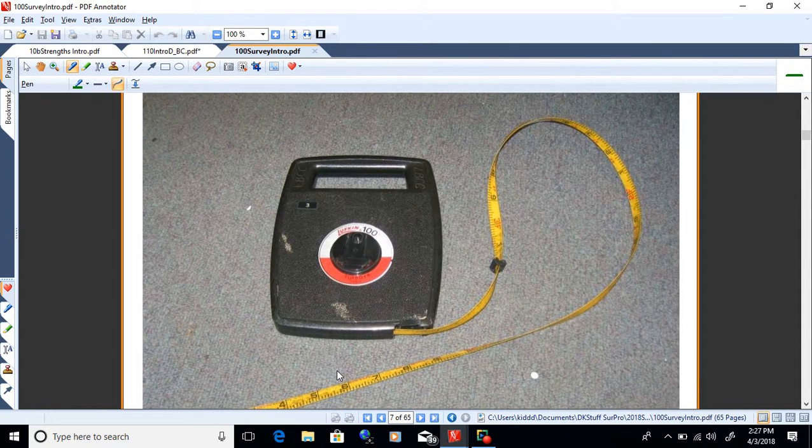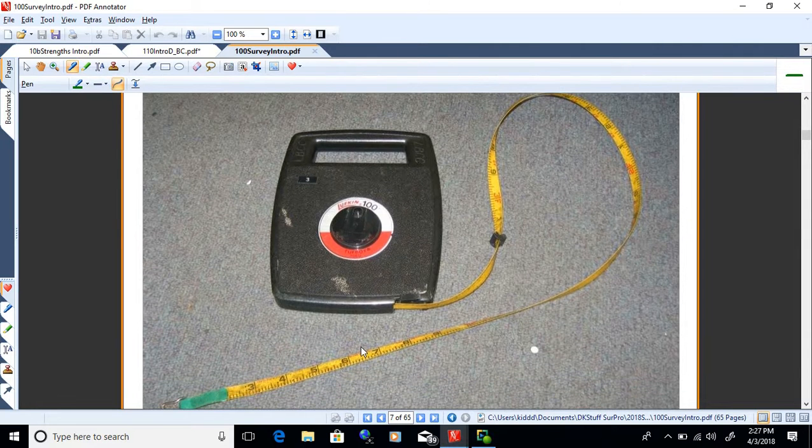That's a tape, okay? So what you do is you stretch that out and measure things. We get a little bit more particular than some other people might in how we hold our tapes and how we stretch them and that sort of thing. But that's a rag tape, as it's called. In the old days, they used steel chains with links on them that evolved into steel tapes. But with the advent of laser type surveying for distance, we don't use the steel tapes quite so much, but we always have these rag tapes, we call these, for checking distances and laying out quick distances if we need.